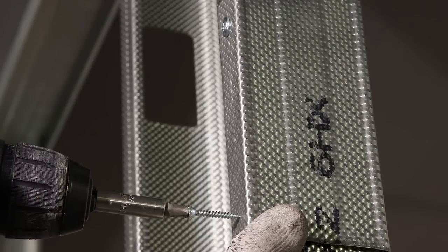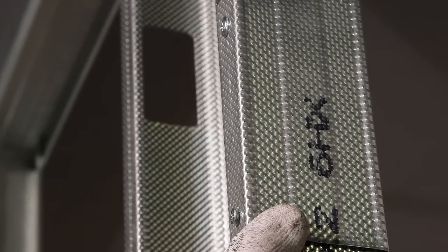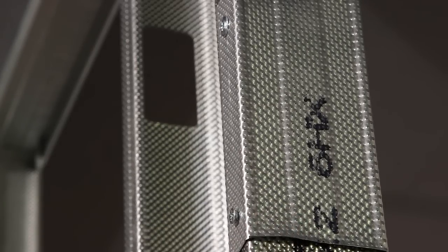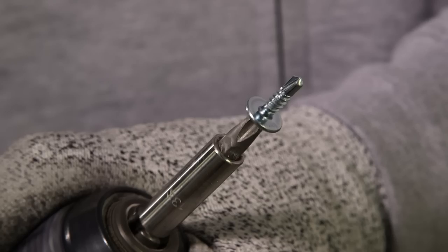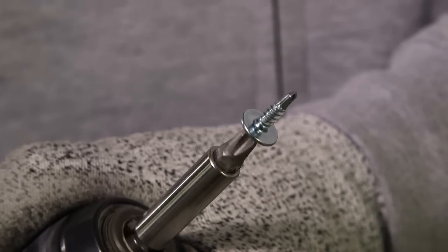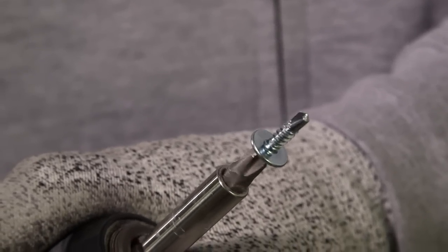Be aware that Gyproc drywall screws are designed for fixing Gyproc plasterboards onto the partition and are not designed for metal-to-metal fixings due to the size of the bugle head, which sticks out on the surface. This can cause bursting of the Gyproc plasterboard when boarding takes place. For heavier gauge studs and channels, Gyproc wafer-head jack point screws are used. This type of screw has a drill bit type of tip, which pre-drills before self-tapping into heavier gauge studs.